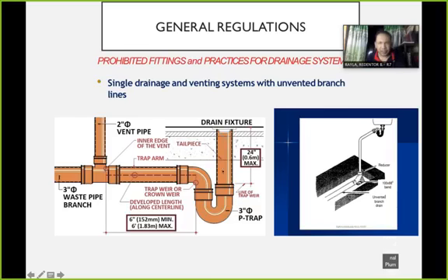So this is what we call tail piece. No? The thing that is between the drain fixture and the trap. We call it tail piece. So it will come out in the board exam. What is a tail piece? Trap arm. No? After the discharge of the trap, that is the trap arm. What is the distance of the trap arm from the bent pipe to the trap? 6 inches minimum. That is the trap arm. May kamay yung trap, so tinatawag na trap arm.